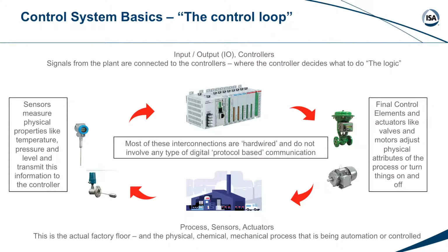So you're moving a big arm on a damper to adjust the air into a boiler or something like that. That entire process is called the loop. And there's a lot of tweaking and a lot of opportunity to introduce error. There's a lot of opportunity to introduce latency or timing challenges with when the sensor is sending its signal versus when the actuator is making its moves.